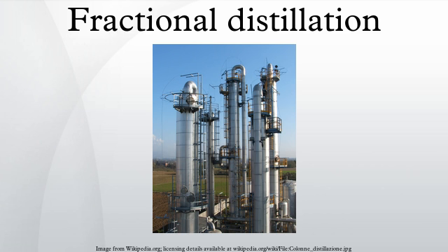Liquids tend to wet the surface of the packing and the vapors pass across this wetted surface, where mass transfer takes place. Unlike conventional tray distillation, in which every tray represents a separate point of vapor-liquid equilibrium, the vapor-liquid equilibrium curve in a packed column is continuous. However, when modeling packed columns it is useful to compute a number of theoretical plates to denote the separation efficiency of the packed column with respect to more traditional trays. Differently shaped packings have different surface areas and void space between packings. Both of these factors affect packing performance.